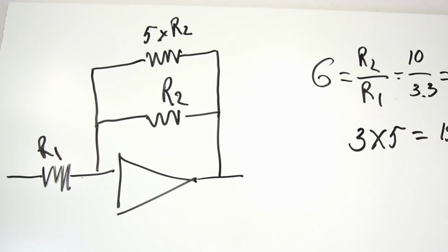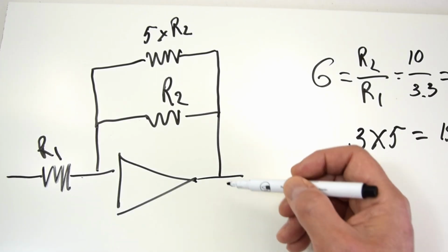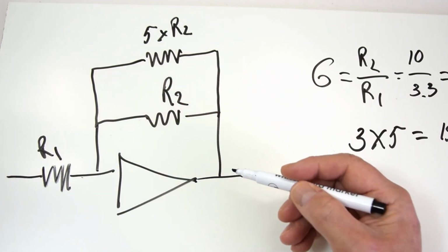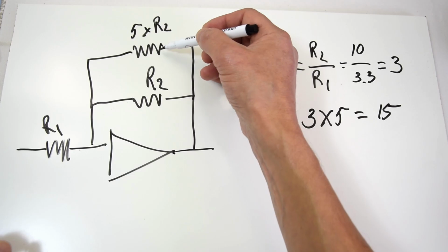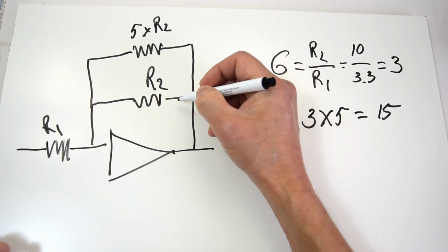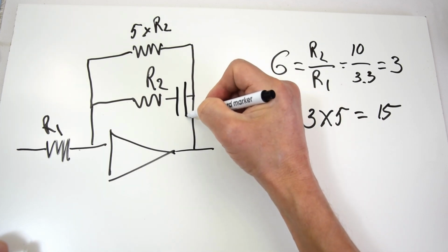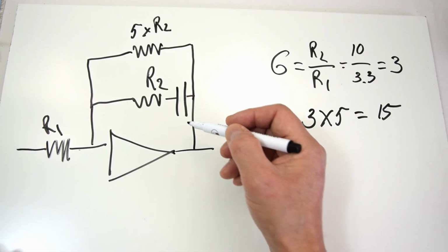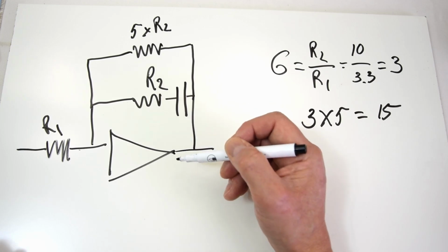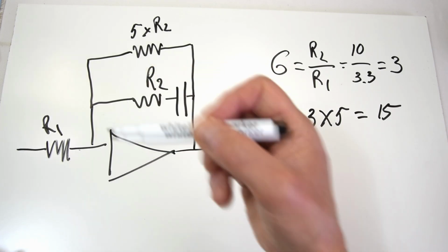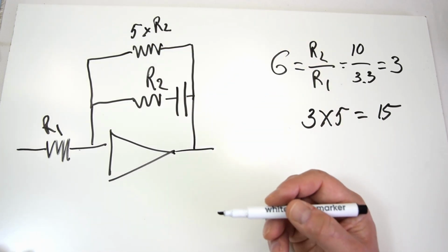The only thing we need is to split the signal, with high frequencies going through the low gain part of the circuit and low frequencies going through the high gain part of the circuit. The way to do that is to place a capacitor. As we know, the capacitor blocks low frequencies and lets high frequencies pass. So if we choose the right value for this capacitor, we can let the high frequencies go through this part of the circuit and the low frequencies to the higher gain path.